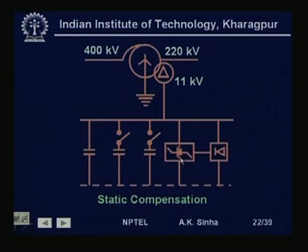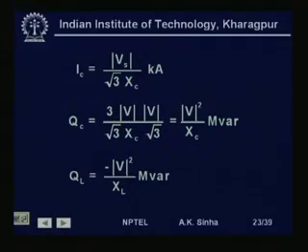The current flowing through this reactor can be controlled, and therefore, this reactor becomes a variable reactor. Using the equipment with these capacitors and variable reactor, we can give any value of compensation that we want. Basically, how much capacitance we are providing will decide how much compensation we are doing.